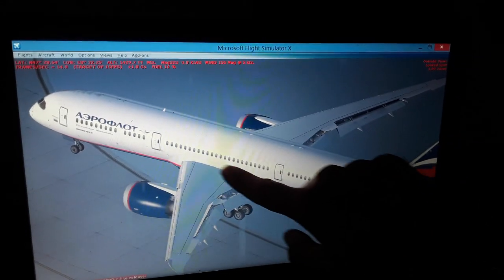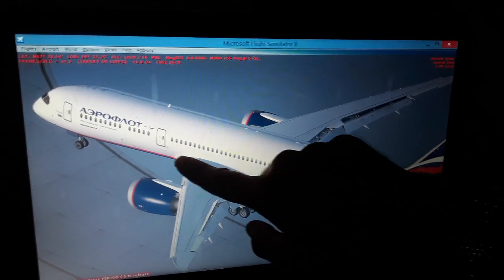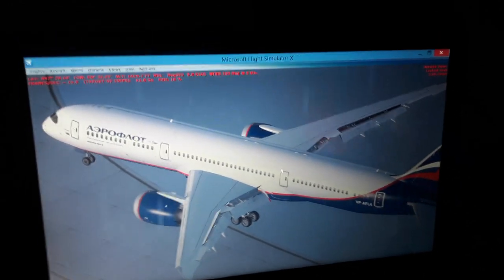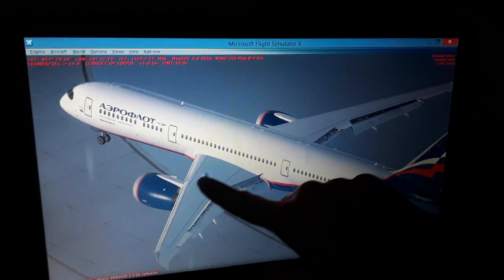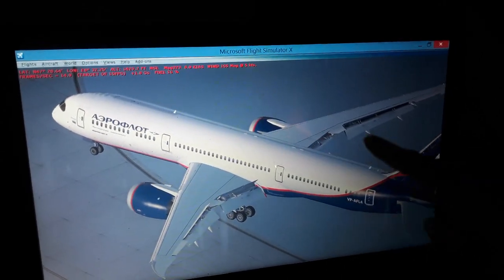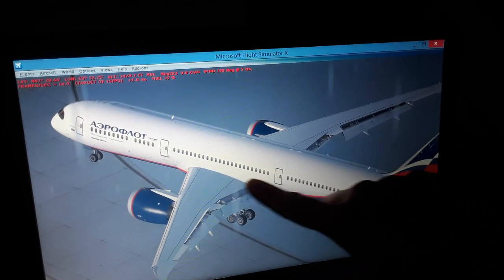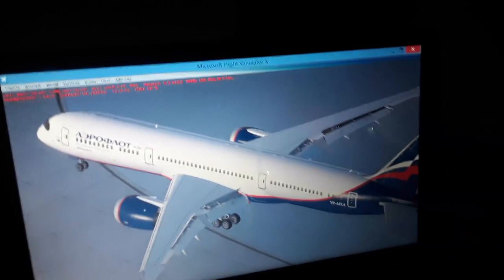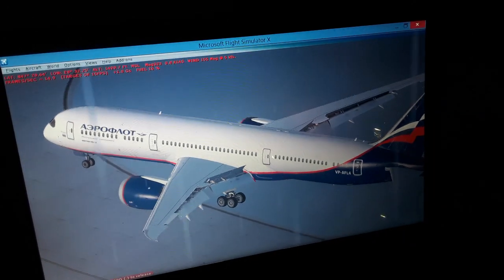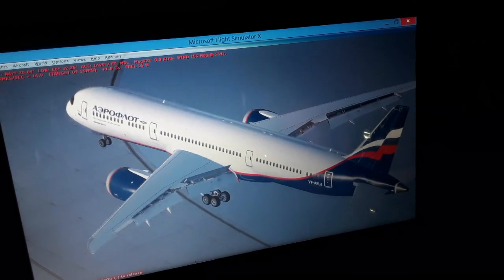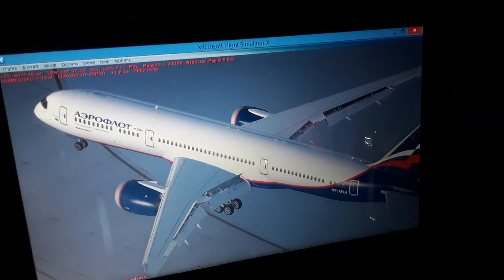We'll have also the center of pressure. You can move back or forward as we fly, depending on the airspeed and the attitude of the aircraft. Also, over here is where the stall will begin in the mean aerodynamic chord position. All the way back, the airflow becomes detached as we fly for a given angle of attack and an airspeed that is changing. It can increase or decrease.